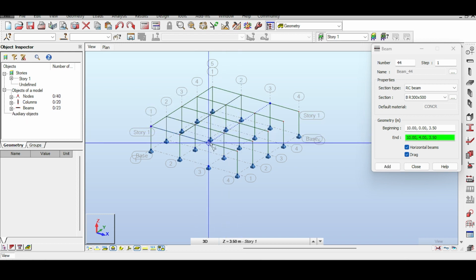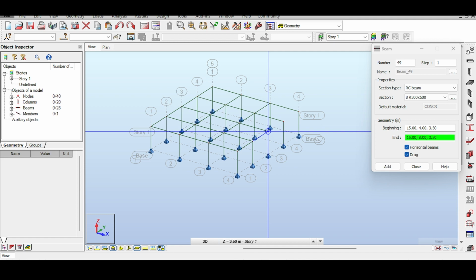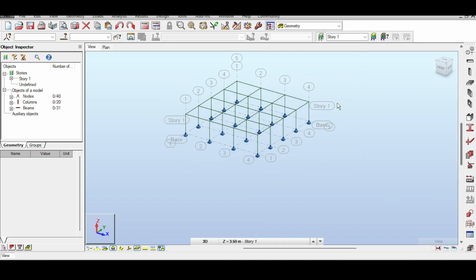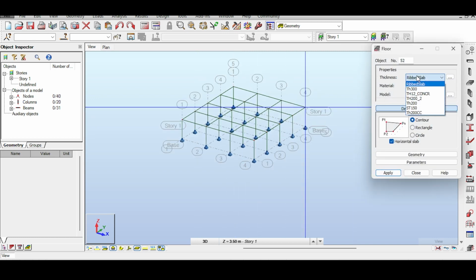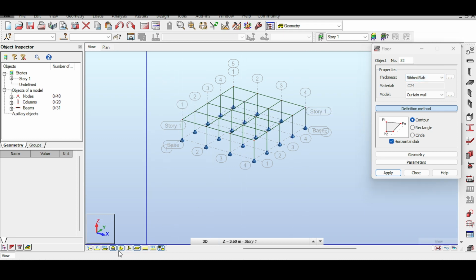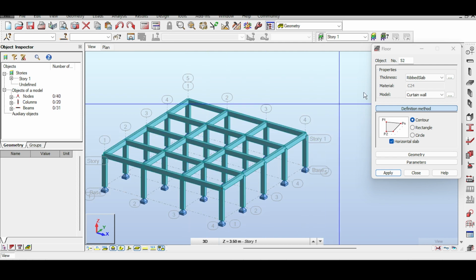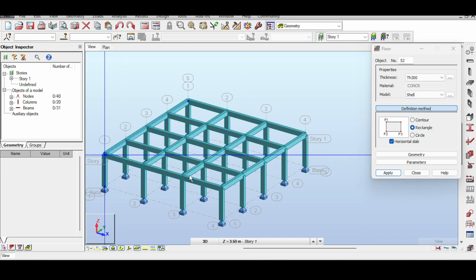You see, I was thinking about doing this on the reinforced concrete building itself, and when I did my first impressions of how fast my video would be, it was dragging too long, and I basically respect your time, so I want to make a simple structure. Okay, so I have beams, I have columns, and they are connected via rigid joints. So it's a 3D frame now. And I'll go to my thickness 300 here for a shell and make a plate or basically a slab.